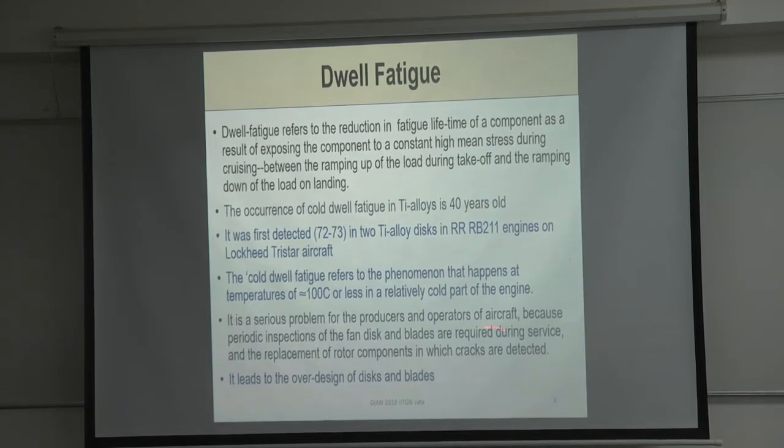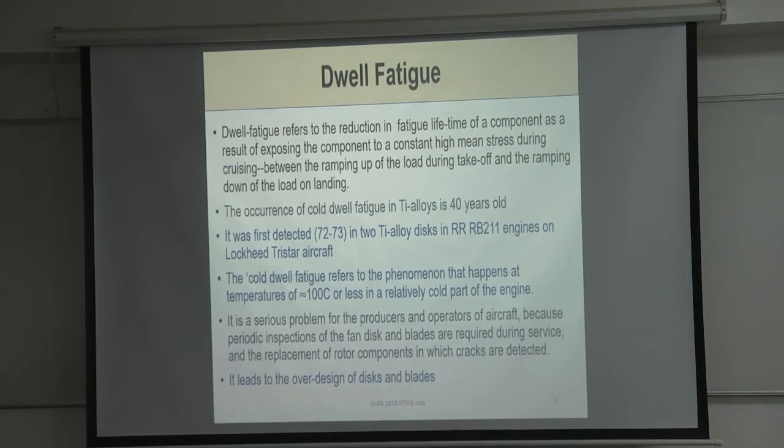So periodic inspections are required, and replacement of rotor components, which is the same as disk components, in which cracks are detected. This used to happen, and it still happens every now and then, and it leads to the over-design of disks and blades. It makes the engine heavier because you don't want to take a chance.